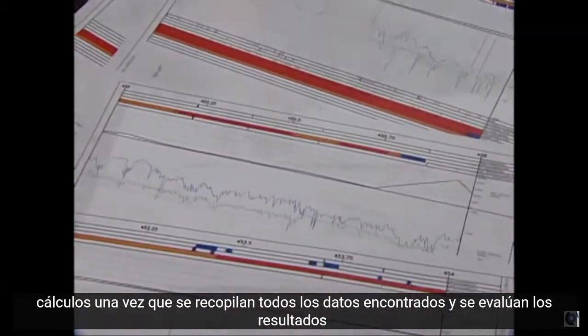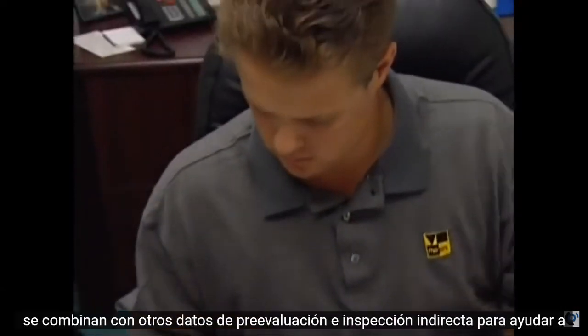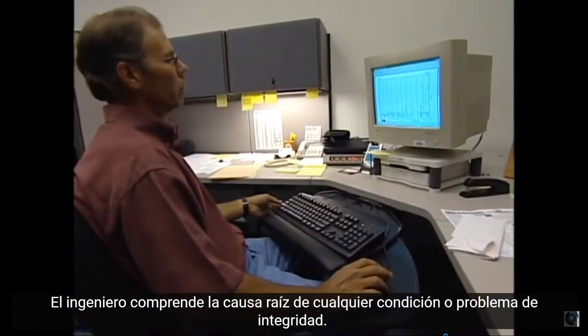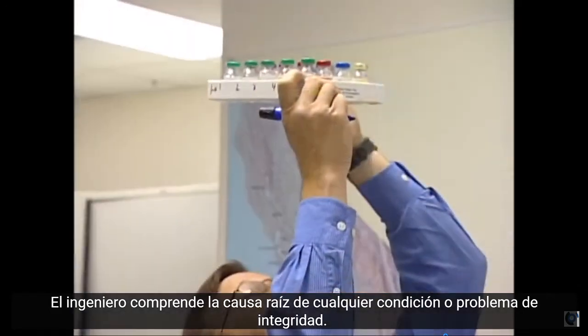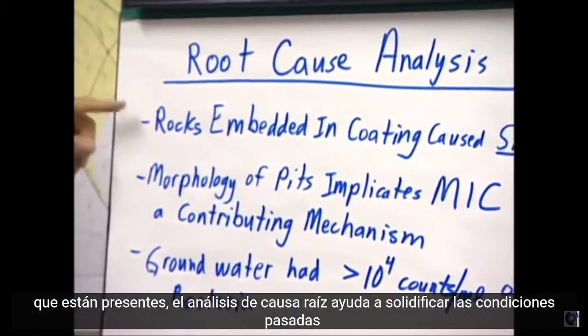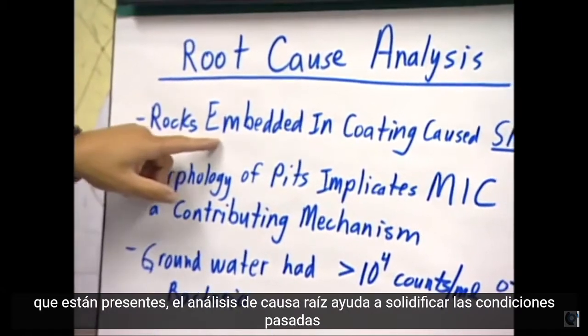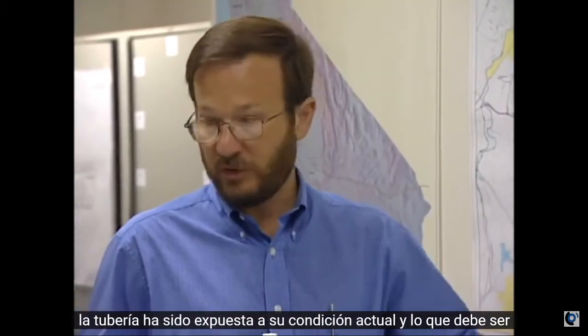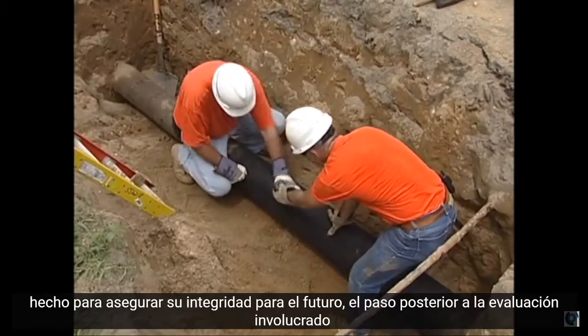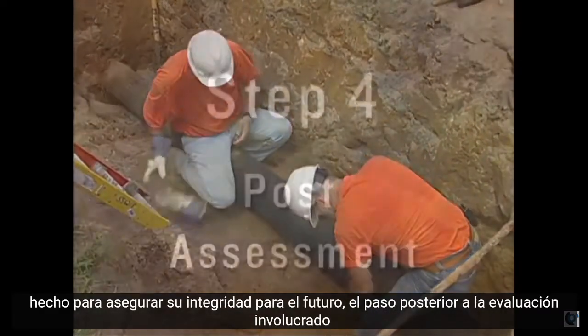Once all the as-found data are collected and evaluated, the results are combined with other pre-assessment and indirect inspection data to help the engineer understand the root cause of any conditions or integrity concerns that are present. The root cause analysis helps to solidify the past conditions the pipeline has been exposed to, its present condition, and what needs to be done to ensure its integrity for the future.